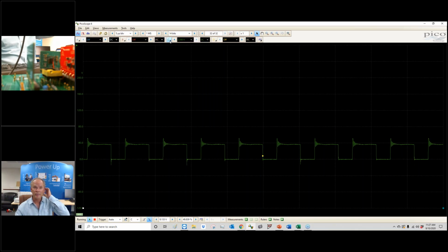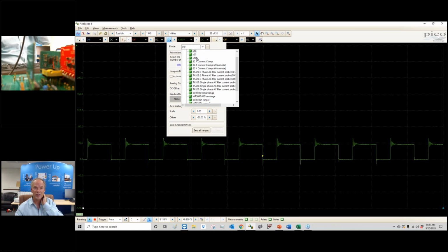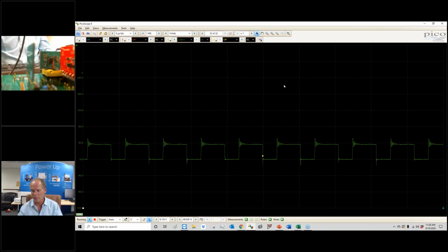So you just take a 10 times or 100 times probe, and then you've got the extra voltage range. If you think about it, we like to think of a scope as working with really high voltages, but no, it counts on the divider first. You can't just put a one-to-one probe. And I think this one is protected at a couple of hundred volts before you can blow it up. So it's a really good functional scope. We run our labs off the scope now just because they're so much more mobile. Okay, any others? Ring coil tester. That's the same thing, you measure the frequency response.